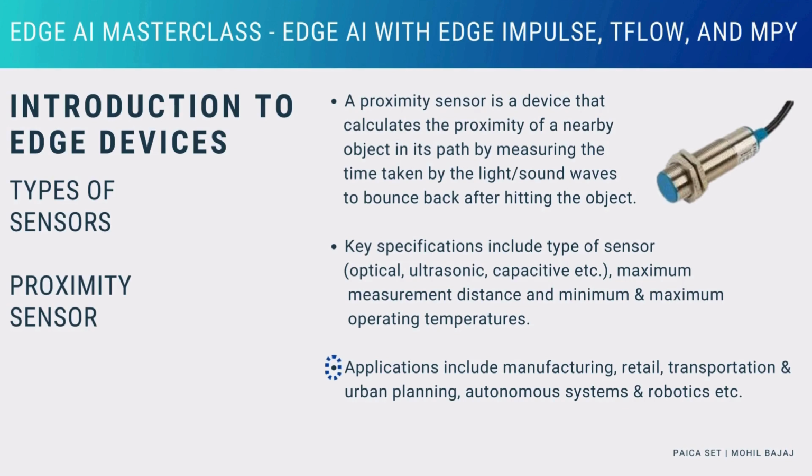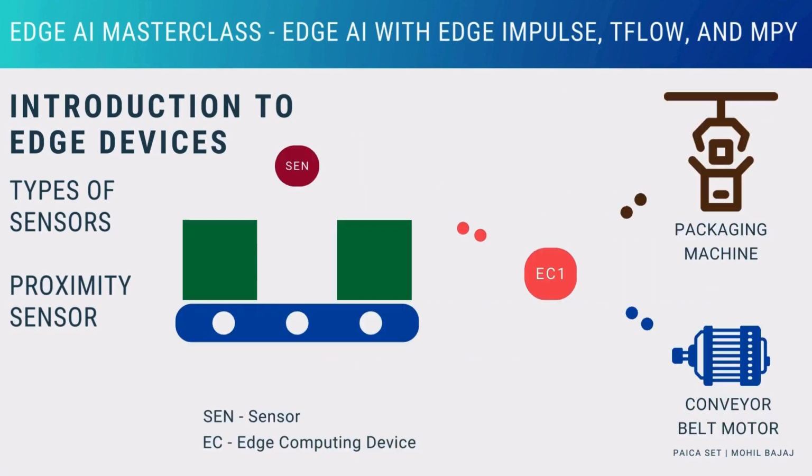In manufacturing, proximity sensors can help automate production lines by detecting the presence or absence of parts. This knowledge can then be used to decide whether the next operation should be performed or not. For instance, on a packaging conveyor line, if packaging material was missing, the line could be moved forward one more step. If not, the packaging machine could be instructed to place the product inside the package and close and seal the lid.